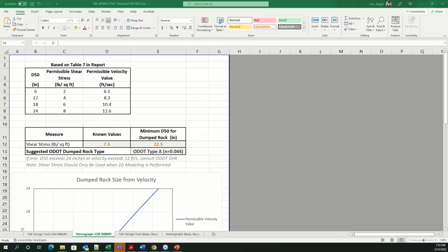Yeah, so thanks, Jeff. That's a really good point. What usually happens is when you compare a 1D and a 2D, you get a different answer. And so when you start talking about what you are going to do inside of a FEMA regulated flood zone, and how you are going to handle that discrepancy between the tabular values and the model values in a 1D domain versus a 2D domain, that's got to be worked out from a regulatory standpoint, because there are definitely differences between the results that you get between the two models.